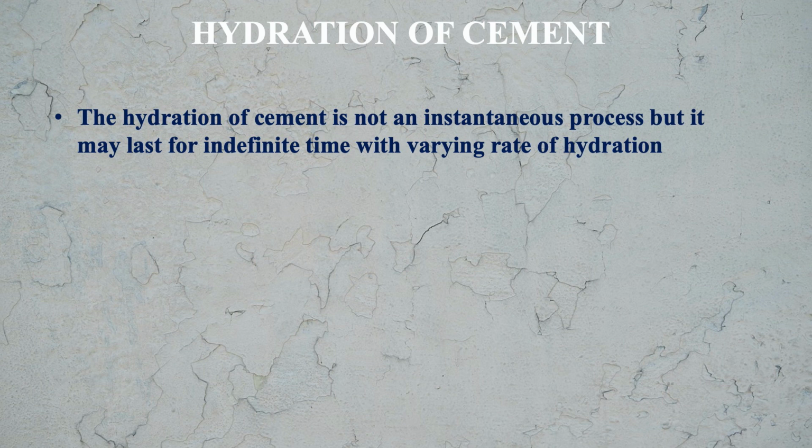The hydration of cement is not an instantaneous process, but it may last for infinite time with varying rate of hydration. Means it is not a process which occurs at a very instant of adding water. It starts at a faster rate initially, but goes on for an indefinite time, but the rate of reaction decreases with time. So this is a very peculiar thing about this hydration process.